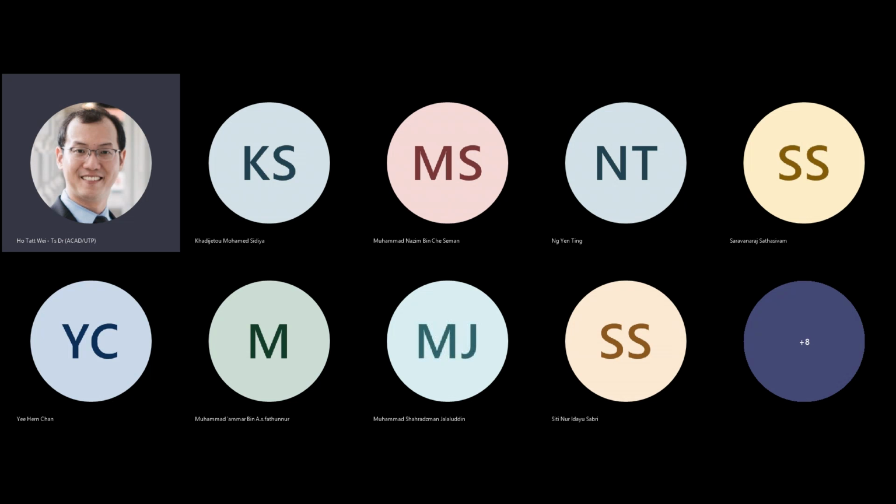Why? As we will soon see, width and length are some of the design parameters for you to control the current that is flowing through the transistor. You call it the drive strength of the transistor, because we are doing all our computations with voltage and current. So we apply certain voltages, logic 1, logic 0, and then there's current that's actually being conducted through the MOSFET transistors, and the capacity of those MOSFET transistors to drive the current is directly related to the speed of the device. Let me repeat that. We care about current because the greater the current your MOSFET can actually source, can actually handle, the faster your device will be.